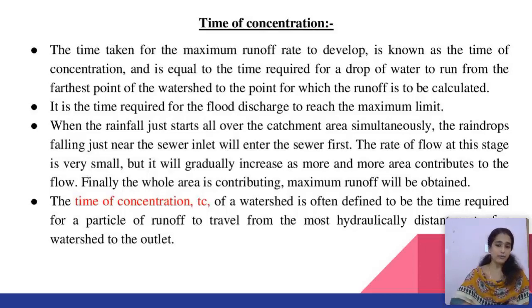Due to that rainfall, maximum flow should reach these sewer pipelines, and this maximum rate depends on the time of concentration. This time of concentration is the time required for a drop of water to run from the farthest point of the watershed to the point for which runoff is to be calculated.